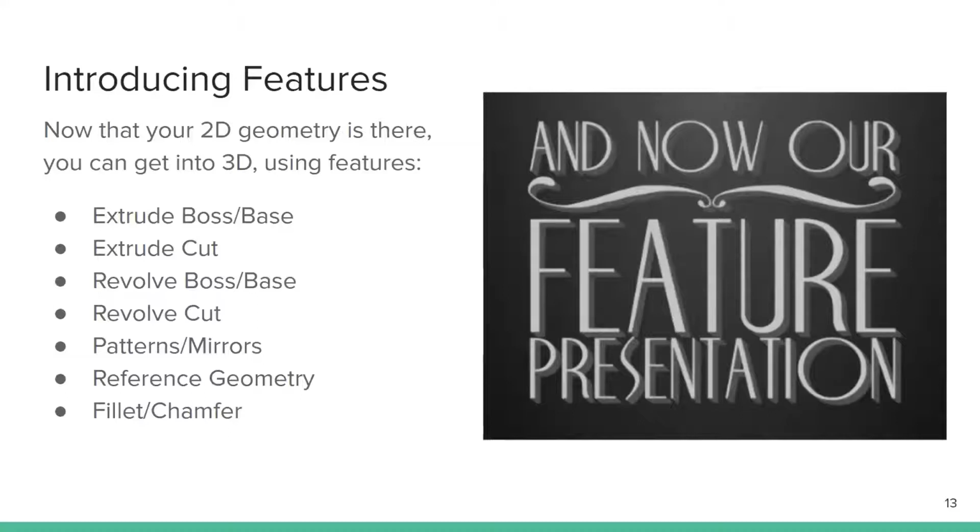Revolved boss base essentially takes a sketch and spins it around an axis of your choosing. So you could choose one of the edges of your square, and spin the square around that edge, and you'd end up with a cylinder. So that would be cool.